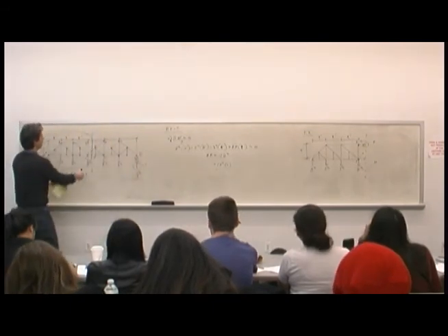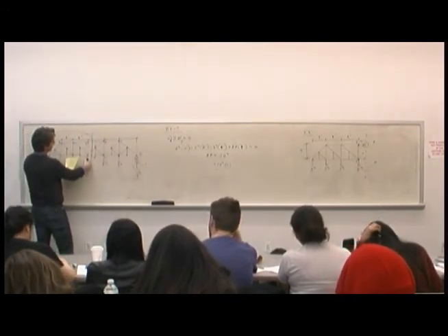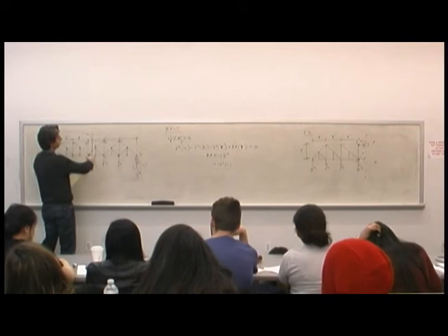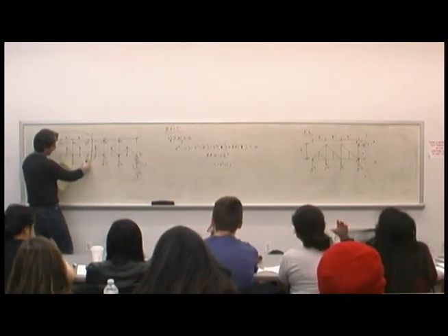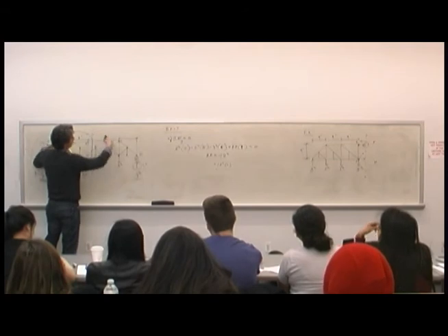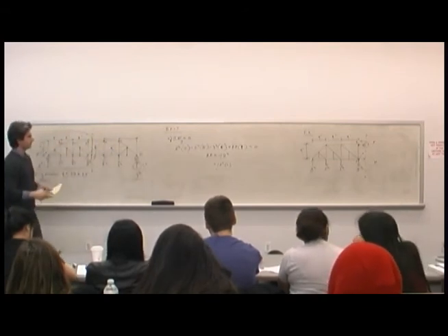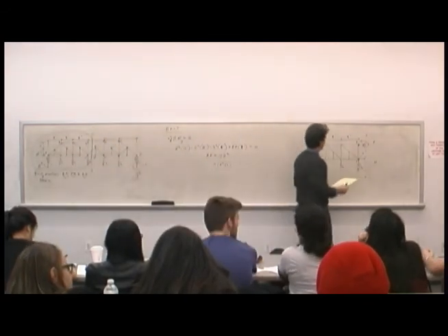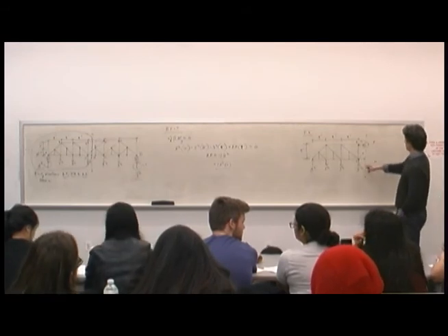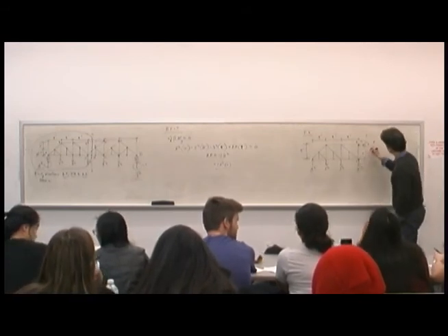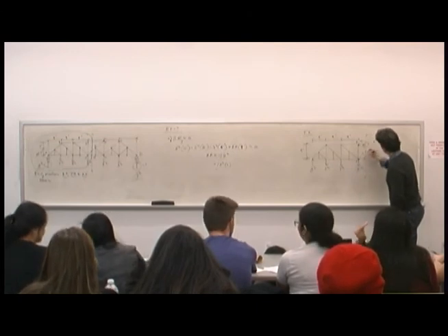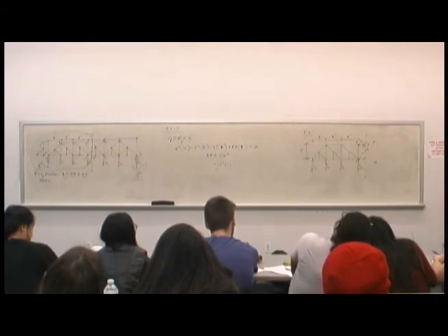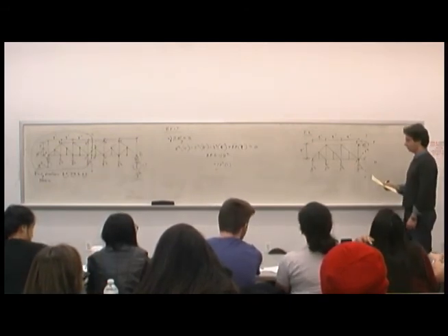Okay, and that makes sense. When you pull on this truss, you pull from the bottom, right? This is elongating, and this is going into compression. You can imagine when you pull down on this, you're pulling all this into tension, and the forces at the top go into compression. So it does make some sense. All right, let's finish out. How do we get JK, which is this element? JK is this little one. How do I do that?